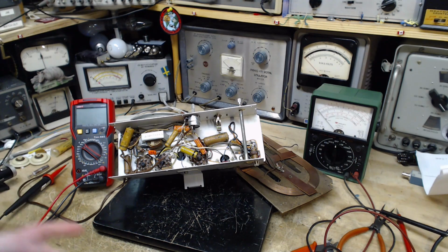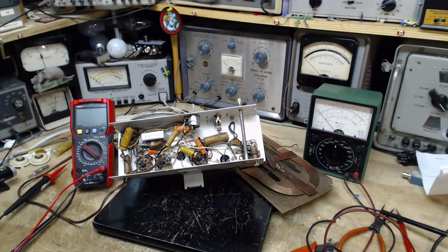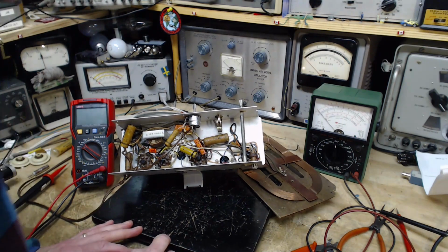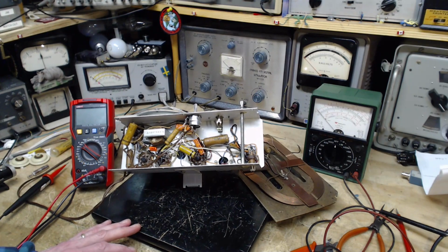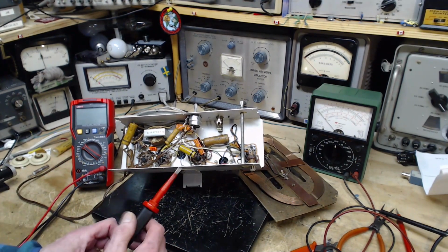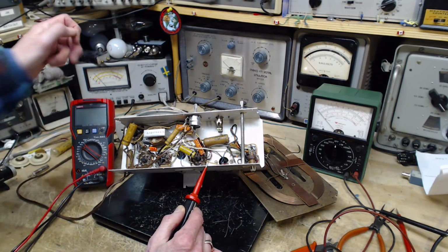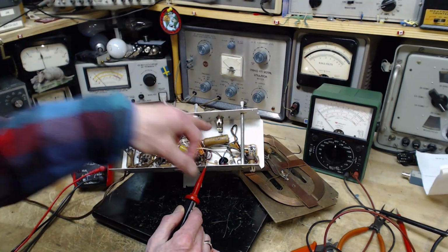It's pretty simple. We just reattach the resistor there, which is fine. Change this capacitor, even though it appears to be pretty good. We can do this. Okay, watch that meter, and I'm gonna push this capacitor back on.